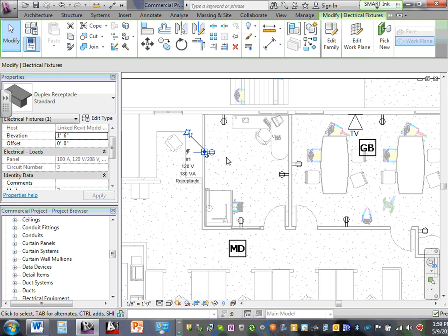If you try to circuit and it doesn't give a circuit, you know what happened? It will happen with you guys. You ran out of 42 circuits. Do you see how important that number is that we put in? If you left it at 12, the minute that you hit 12 and go to 13, it wouldn't allow you to circuit. Why? Because you don't have room in your panel. Any questions, guys? See how easy that is?